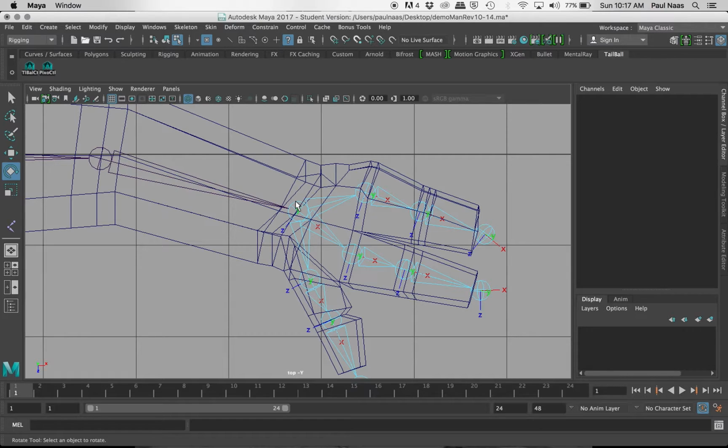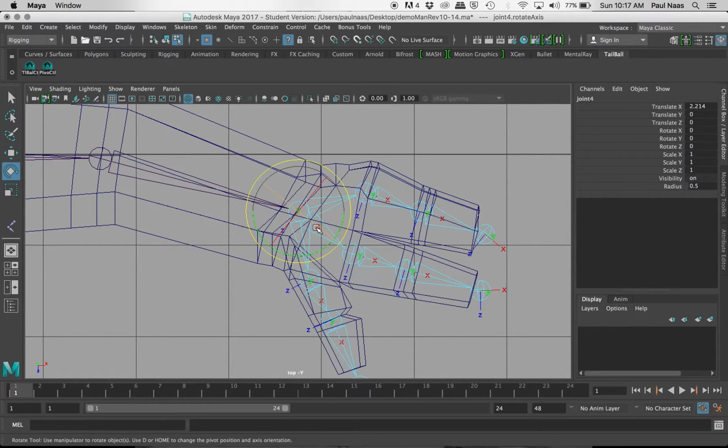And what I want to do is rotate my axis. So I'm going to just use the same rotation tool, select my object, and when I rotate this, whoops, wrong axis, I'm going to turn this so that that little plus inside the joint there lines up with the bone length. And then F8 again. And now I've changed the rotation axis of the joint so that it lines up with the bone.